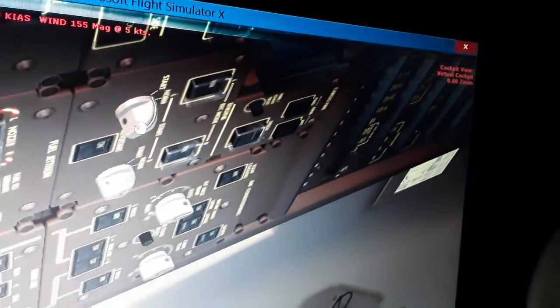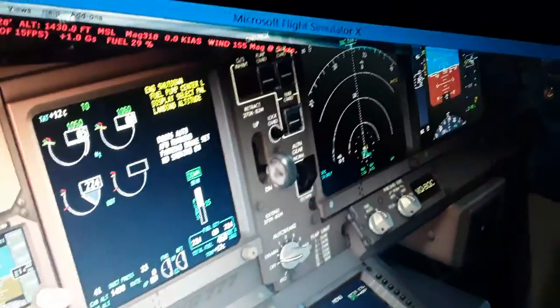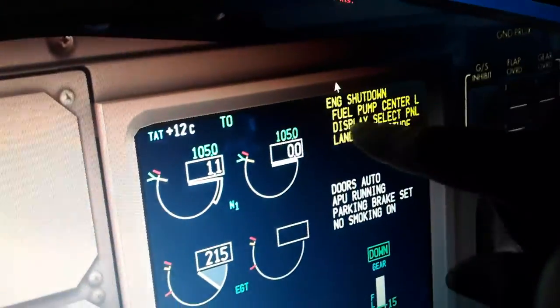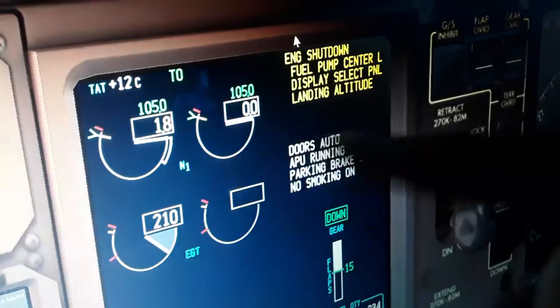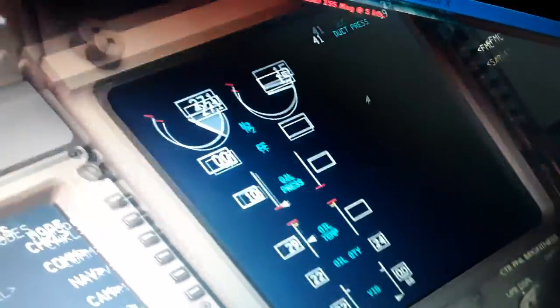First, the left engine. Here is the engine starter for the auto start system. So you're gonna see many reconfigurations here. You're gonna see the engine shutdown indications, and also the N1 increase, the exhaust gas temperature, the N2 increase above 20%, the fuel flow.